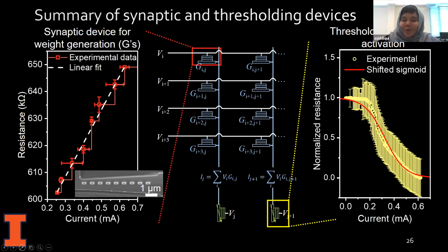That is a very good question. Whenever you create this system, you need a certain filter, and they have to be varied based on what data you are processing. In most cases, you don't have a system large enough to load all the filtering data or all the inputs at the same time. So there is some limitation, and there is some data shuttling. When I'm talking about the change in the synaptic weight, that's comparable, but the interconnects are involved, and that's still a killer factor until now. So it's not very soon that it would be comparable to the biological system, but maybe in some future.